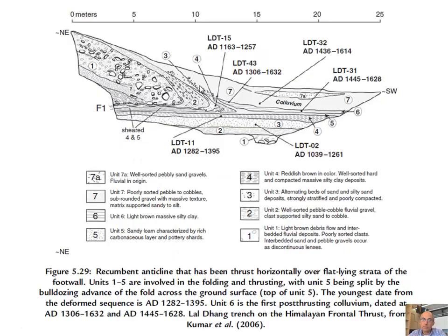So then finally, this is Himalayan, another one, Himalayan thrust front. So again, showing the nose of the hanging wall just driven out into the topography in front, and then their efforts to try to date it. So they, I think, would put the earthquake, obviously it breaks through here, and these layers somewhere about here is post-earthquake, like this colluvium. So they can date the colluvium at 1436, but then somewhere around here, 1306, or here, they're for sure older than the earthquake, right?